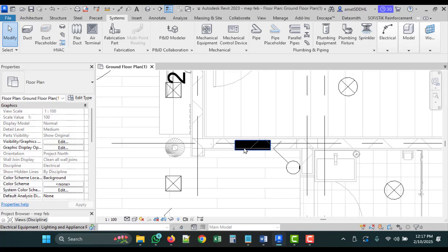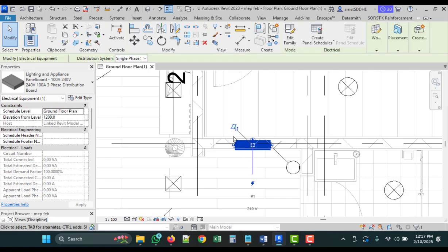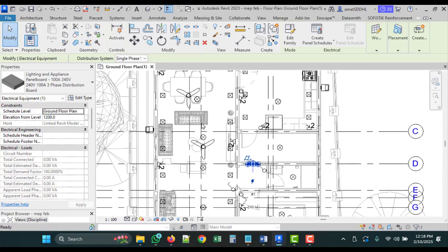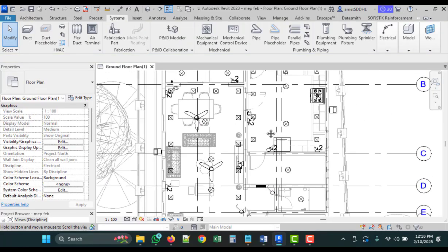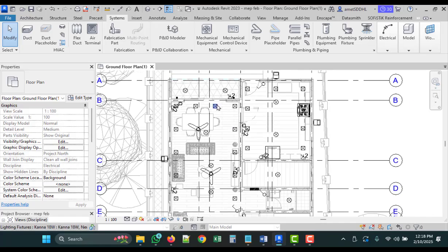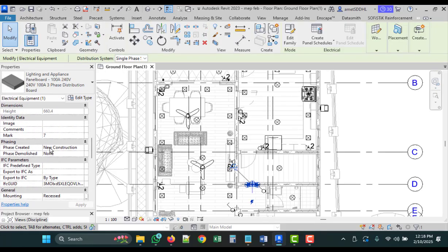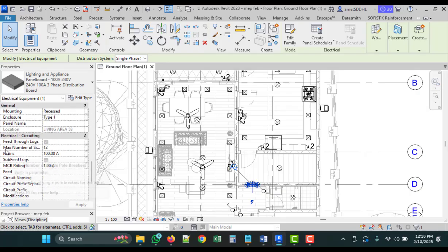All right. So now we have successfully set up our distribution board. So it's time to connect our lights to it. As we discussed earlier, we are going to start with connecting all the bedroom lights on one circuit to the board. This particular circuit actually has 12 breakers, and the mains is 100, as stated earlier. So if you want to change it to 8 or whatever, you can change these values to the number of breakers that you need on that distribution board.